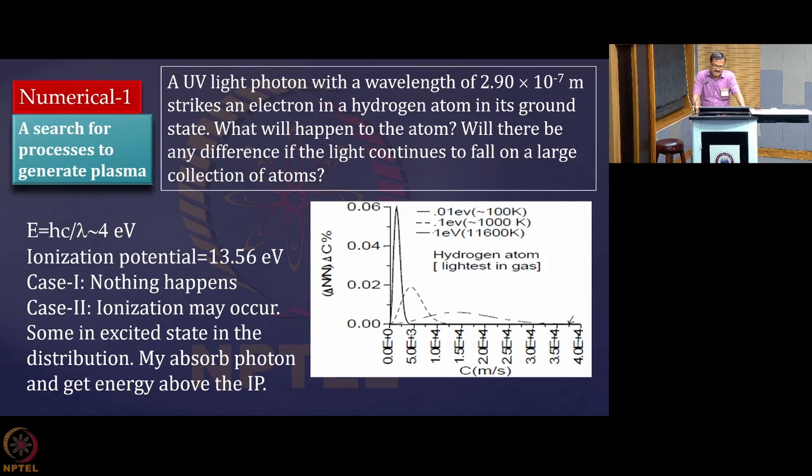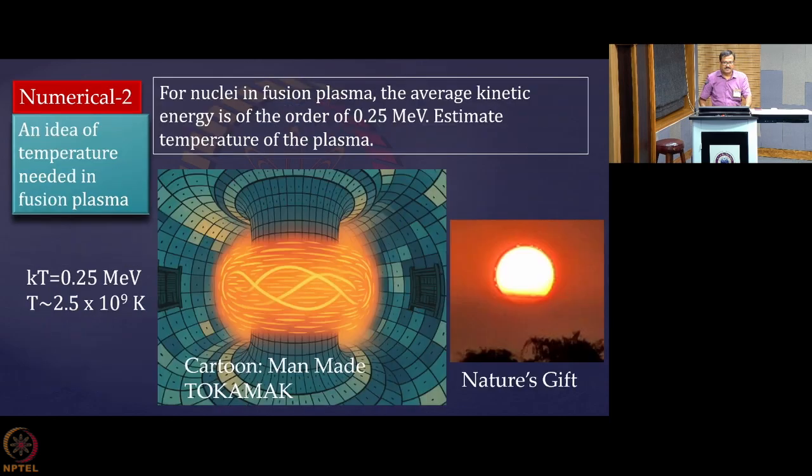If the atom in the excited state receives a photon of this kind, that can ionize. That is the way you can get a pretty good amount of ionization. And if you are assisting that through the application of an electric field, that may cause breakdown as well. So this is a fundamental process which should be kept in mind while you are analyzing the other effects.